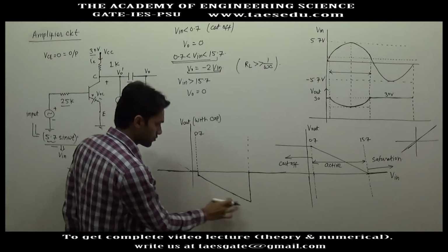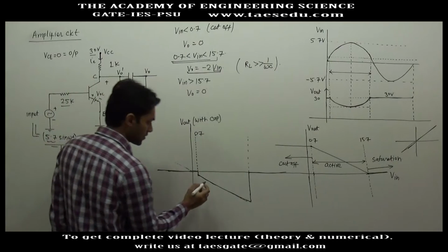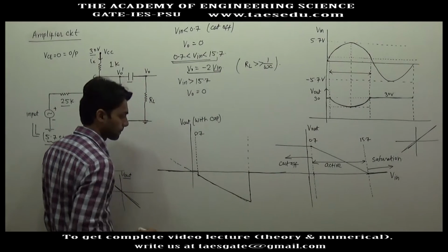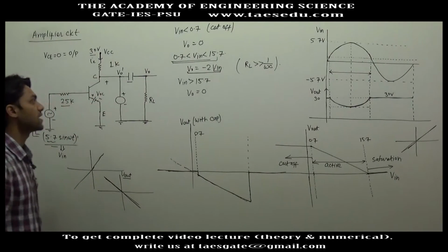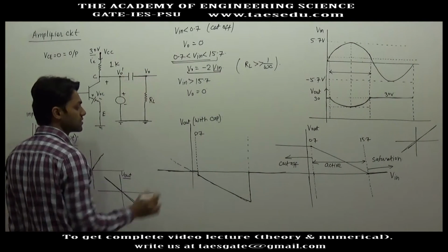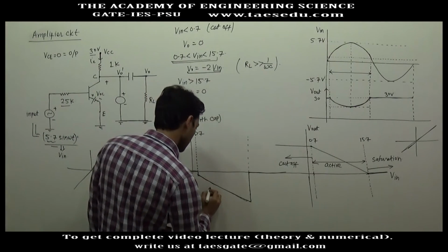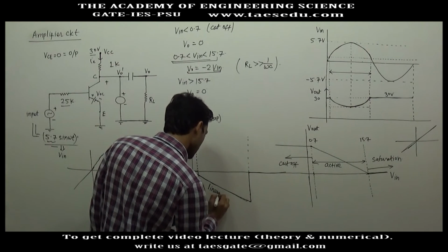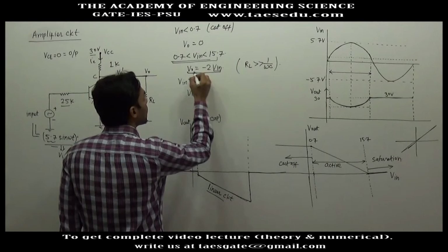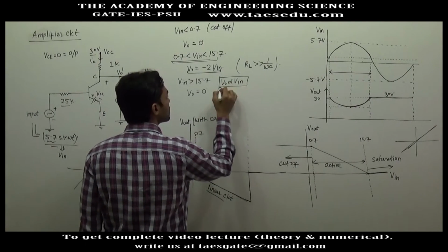So in this part, what you are observing, if you connected a capacitor, how is this response? If you extend it, this will be passing through origin. So when the transistor operates in active region, and now you are removing DC parts, the graph becomes linear. This becomes a graph of a linear circuit, where output is directly proportional to input, and this is the condition for an amplifier.